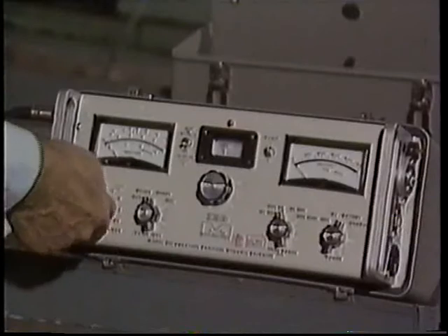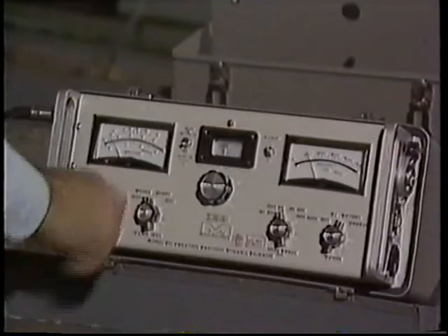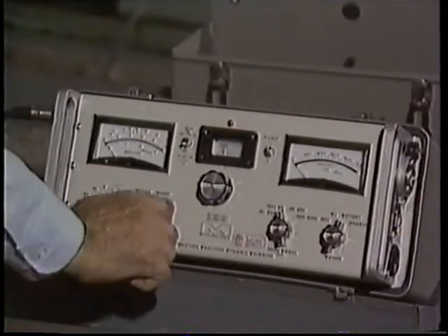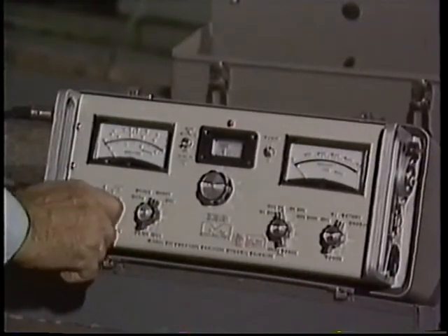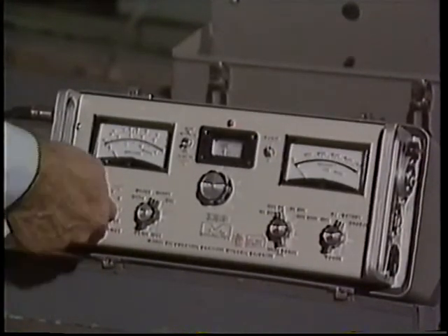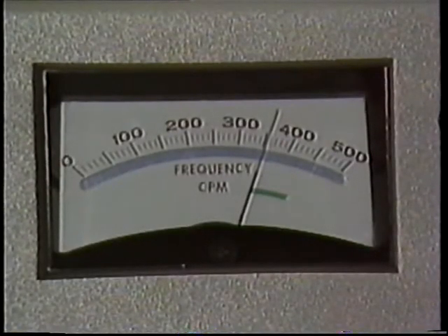The broad filter function on the analyzer allows you to scan through each filter range until you find the frequencies or peak amplitude. Then you can use the sharp filter function to tune in on these frequencies. In this way, you can get the most precise readings possible. These readings are the ones you need to pinpoint the source of a problem in your machinery.